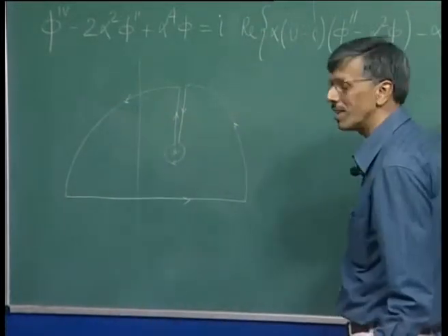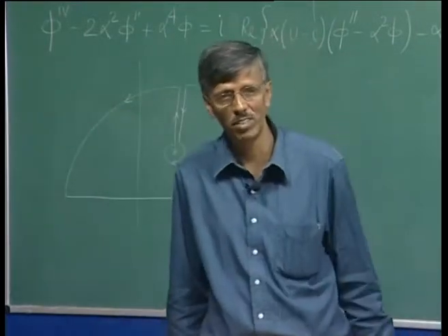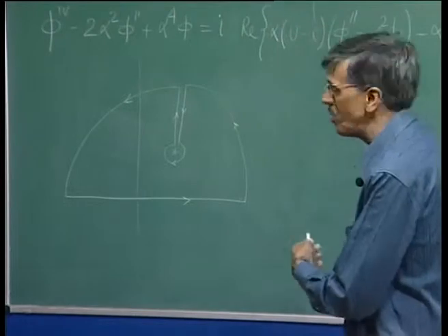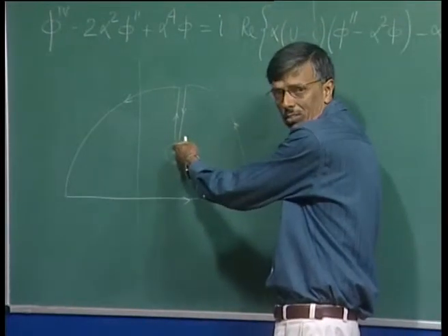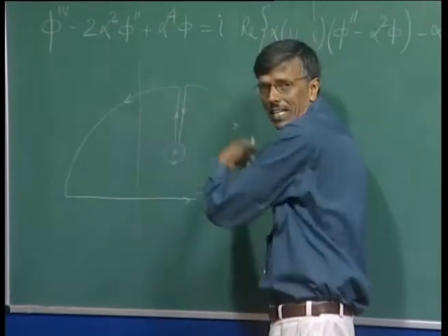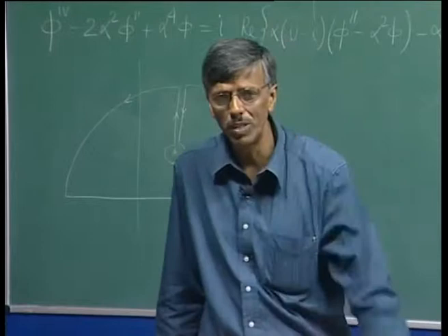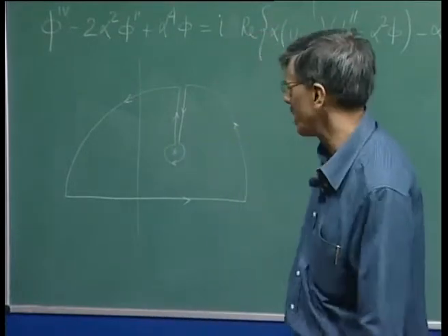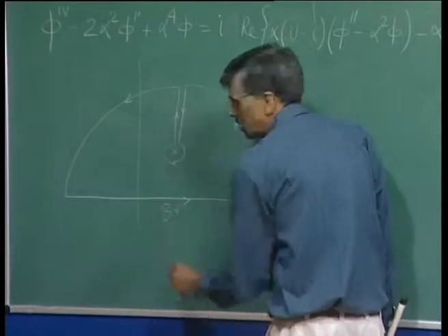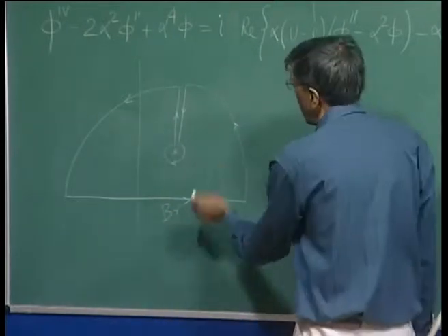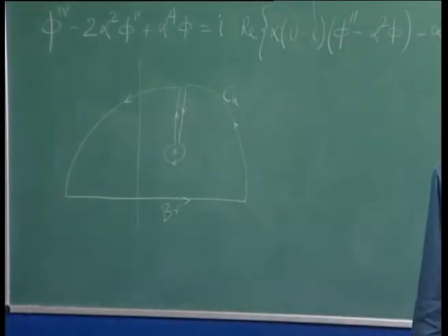So, we are showing the connection between receptivity theory and instability theory time and again, and this is the way we go about doing it. We exclude the singularities, so that the function is analytic everywhere, and then we say by Cauchy's integral formula it should be equal to 0. It should be equal to 0, it is fine, but then it has a couple of contributions. One comes from the Bromwich contour, the other comes from the contour which is in the upper half plane.